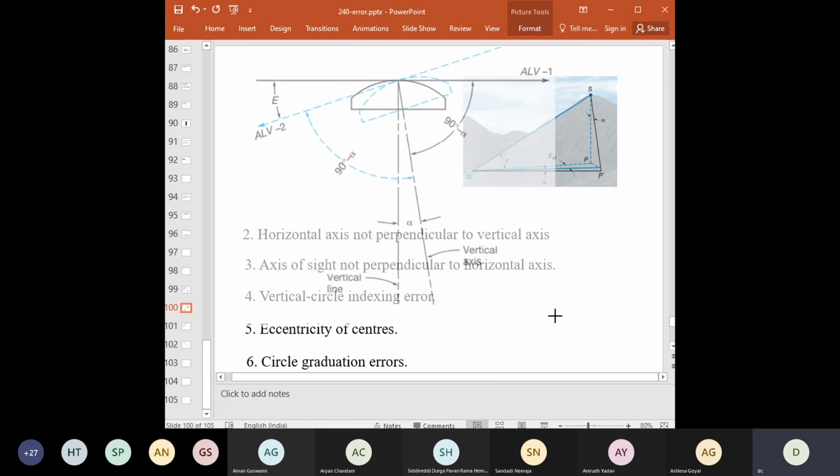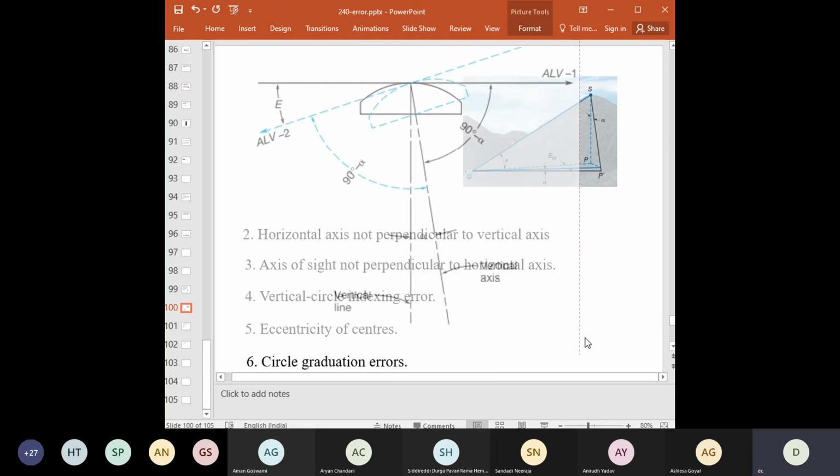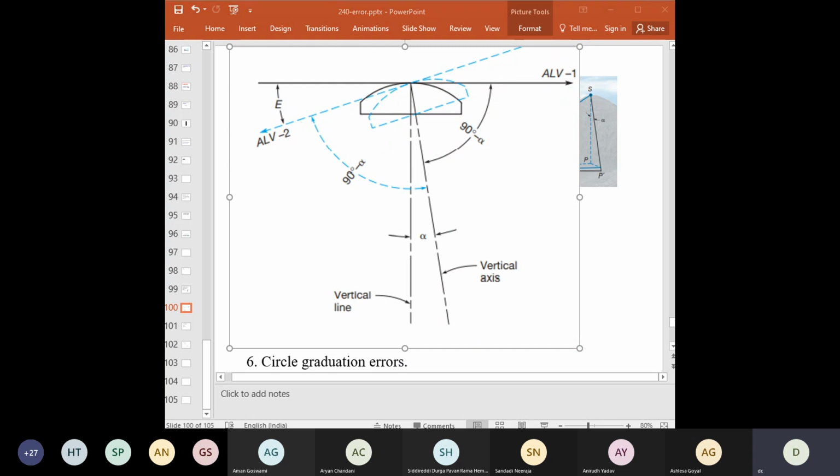Okay, so what happens in the process is some geometry which comes up like this. With the telescope, the plate bubble is out of adjustment if, after centering, it runs when the instrument is rotated 180 degrees in the azimuthal direction.